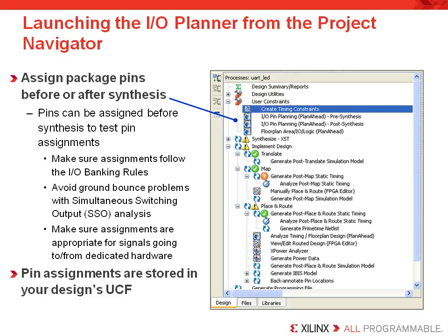As I mentioned earlier, your pin assignments are stored in your user constraints file, which employs a user editable syntax. By having a single text file to hold all of your pin attributes and constraints, even when using PlanAhead, the overall FPGA design flow is simplified. So if you have not already opened this file, the next time you're running the tools, crack the UCF file open and try to get familiar with the basic syntax it uses.